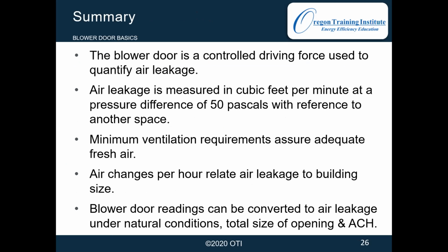So we went through how to use the different calculations in conjunction with our manometer to calculate flow. Well, the manometer is doing that part, but we can calculate the approximate leakage area and figure out how big the leaks are. We can quantify it, so we can determine how much difference we made before and after.